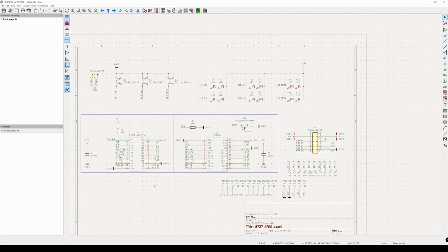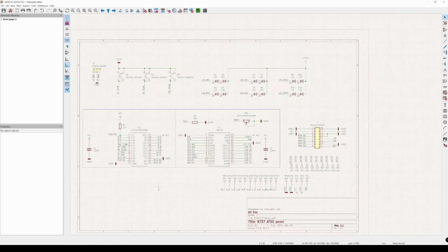Or will it just be floating somewhere, right? So for mounting the PCB you would usually use screws. And adding screws to the schematic might seem stupid, but that is how it is done in the Schematic Editor in KiCAD.